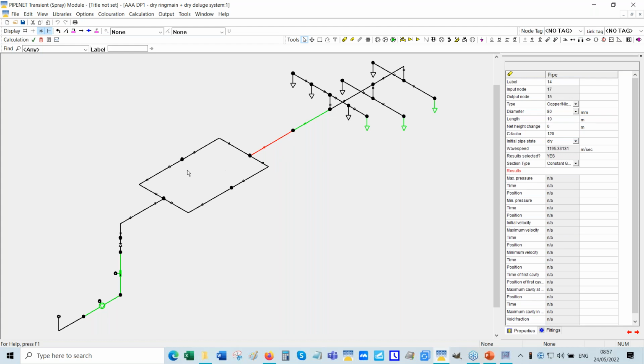Because the water flows at a high rate, because the diameter is so big, and the air gets expelled, the water reaches here, and then suddenly it decelerates. So it could lead to a high pressure surge at that point in time. So you've got to watch out for things like that. Okay.